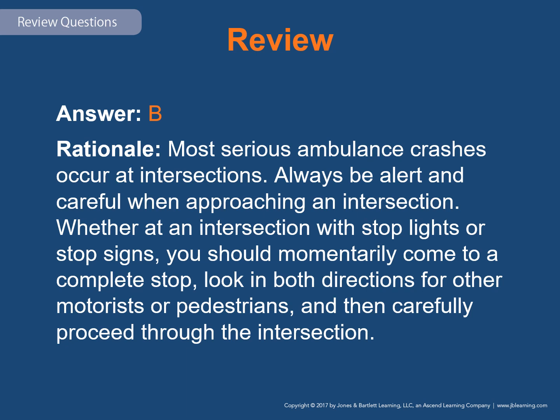Take, for example, there might be a pedestrian who's completely deaf, who has their back to you and doesn't see your wigwags and lights, doesn't hear your sirens at all, who has no idea you're there. And you go busting through the intersection. So, there are a million different scenarios, but intersections are always an issue. People are moving through on a green light, and you're approaching from a side and they can't see you, possibly because of buildings or shrubbery. So intersections should always be treated with very high regard, because that's where most accidents occur.